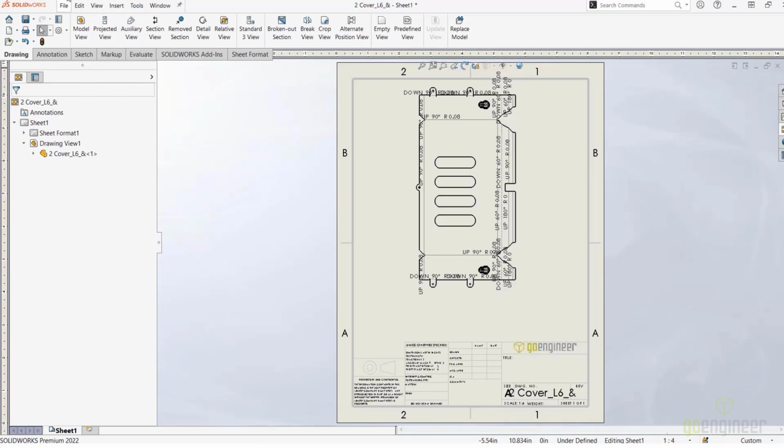In my experience, and I actually had this happen with a customer, if you had any sketch entities visible on your part file and went to create your drawing directly from that, those sketch entities would be visible at the same time when you're trying to show the bend lines that you see here in the drawing. So they've split that up so that you can hide your sketches and show the bend lines all in one step, instead of having to go back, hide all sketches, and then show just the bend lines in your drawing.